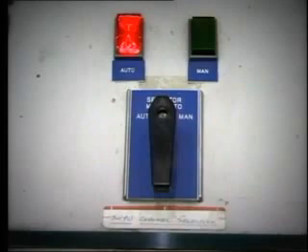The standby pump may be made available for automatic start in case of failure of the running pump and a decrease in feed water pressure. The feed water pump is truly the heart of the power plant cycle and therefore must provide 100% reliability in supplying high-pressure feed water. Make sure that you're familiar with all the mechanical details of your particular feed water pumps and especially the procedures for making the pump available.